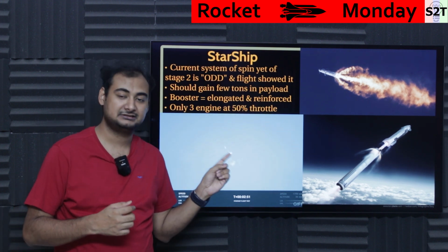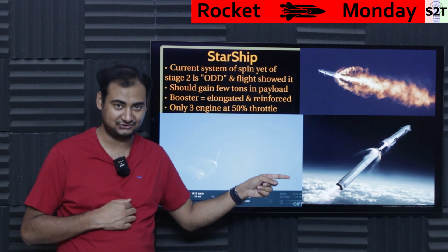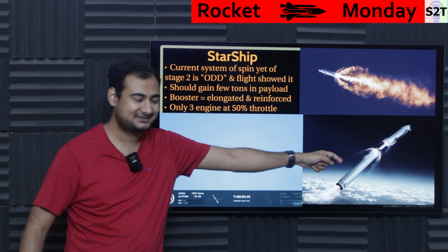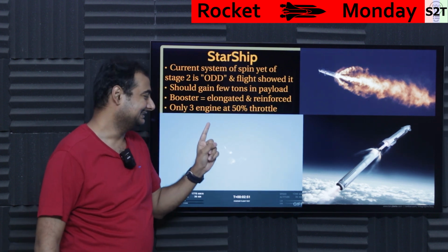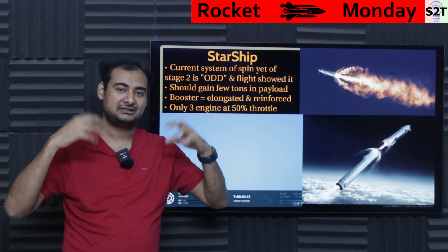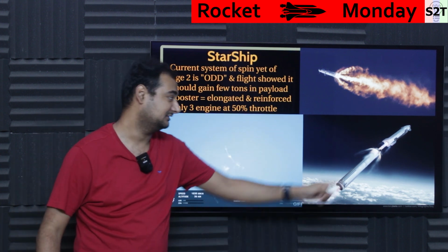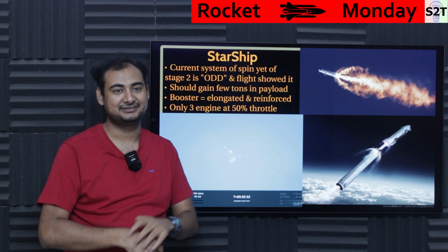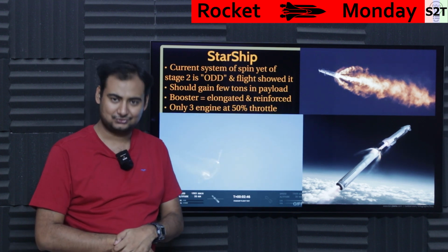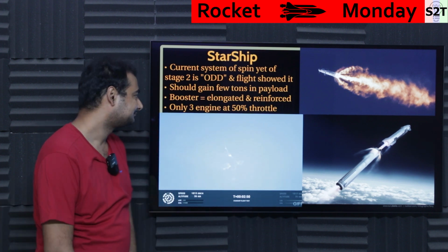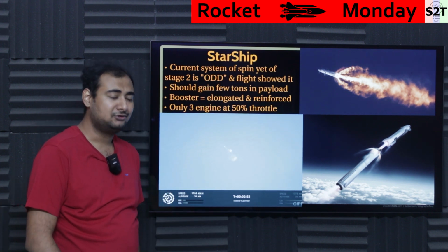Now here, this is the hassle for them, because they want to reuse the booster, and the booster is going to be exposed to direct engine exhaust. So that's a very serious issue. So I do expect their first booster, even if it lands perfectly, they're not going to reuse it. They're going to analyze the hell out of the top part, which literally survived rocket engine firing. So I do expect this will increase the cost of the upper stage of the boosters. So that's there. And how are they going to achieve separation?